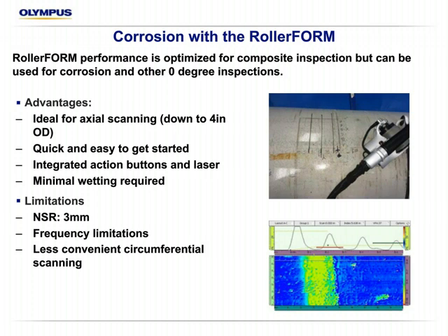So as a general baseline, if you just want to detect the areas of corrosion, then go back and measure them again with dual element, or you just want a general idea of the amount of corrosion, not looking for very, very thin wall, it could be an option.